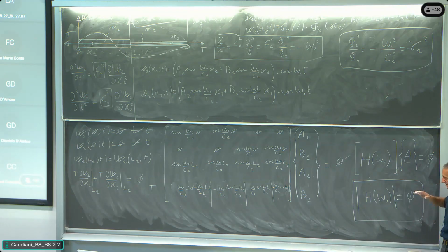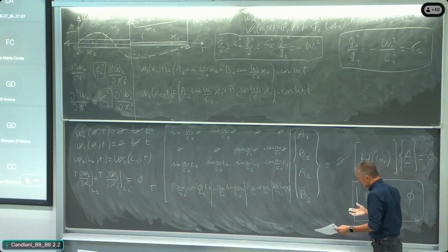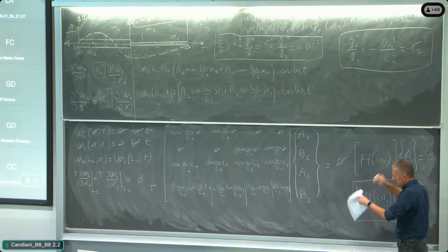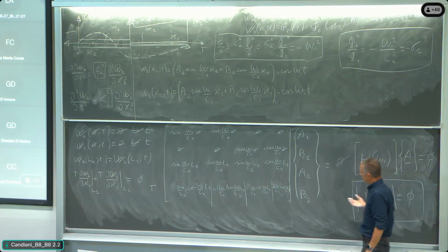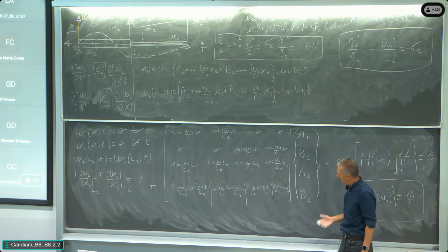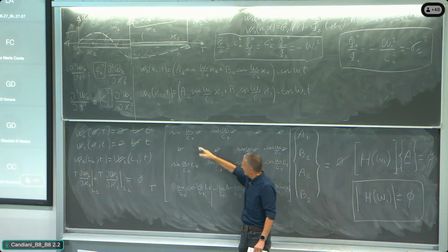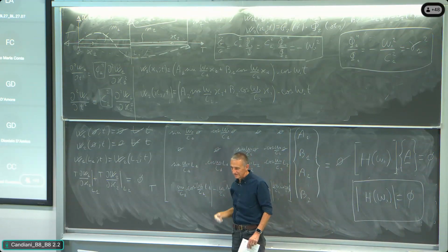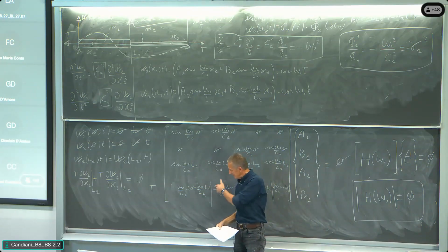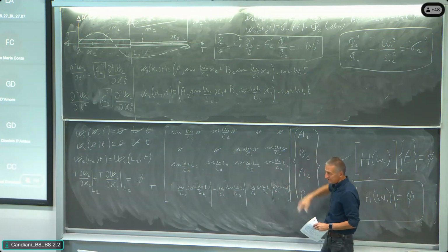And so the way in which we approach those problems in order to write the free motion, the modal shapes, the solution of the free motion of a slightly more complicated problem with respect to the simple tensioned cable, is to understand that now we have this very complicated problem: to find which are the numbers that, inserted into the transcendental, trigonometric functions, make the miracle of giving the determinant of order 4 equal to 0.